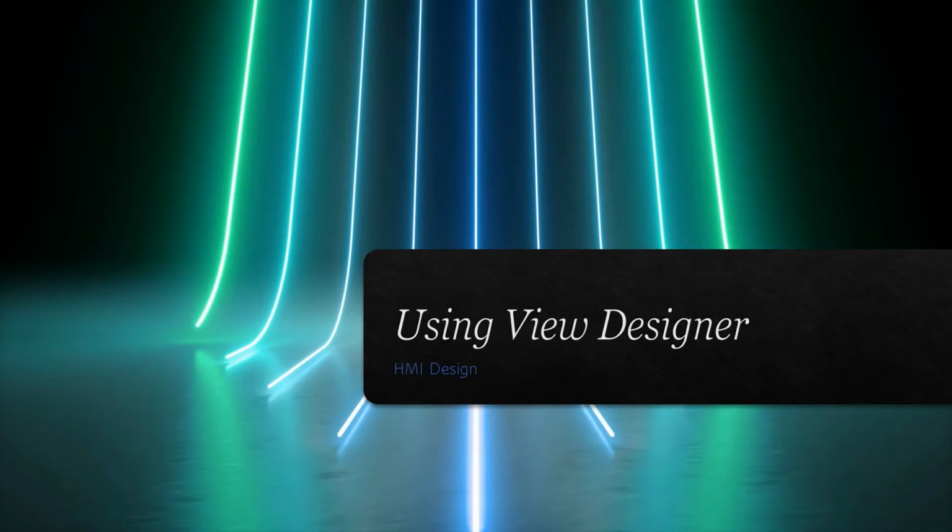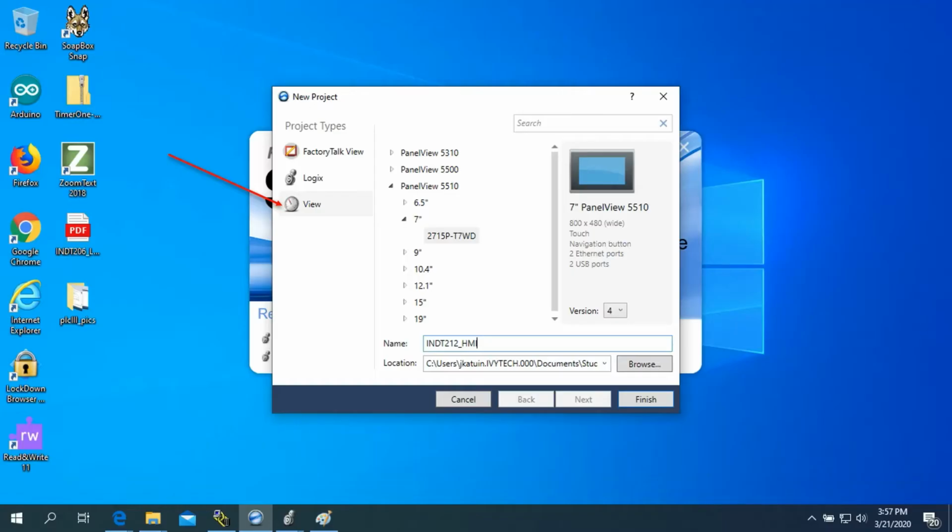So what we're going to talk about now is using View Designer. View Designer is actually another HMI package that's built into Studio 5000 if you're using the 3.1 version or higher. To start a new View Designer project, you would go into Studio 5000 and then select View. At that point, you would have a choice of a variety of panel views to work with. We're going to go ahead and work with the 5110 7-inch panel view.